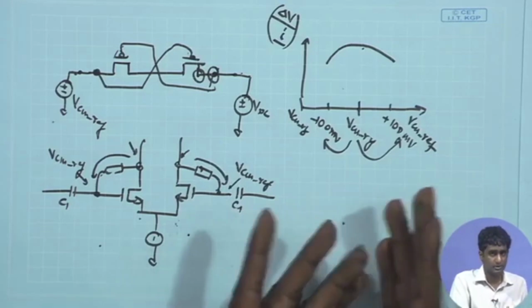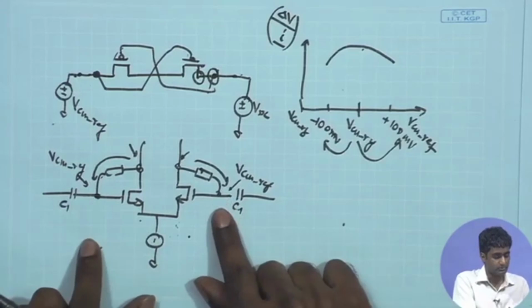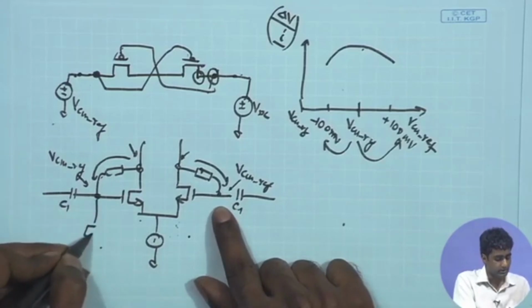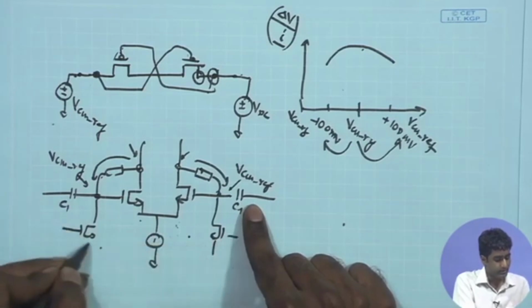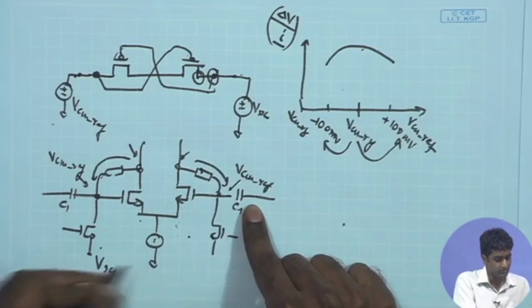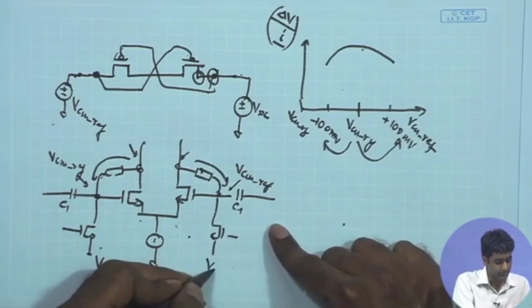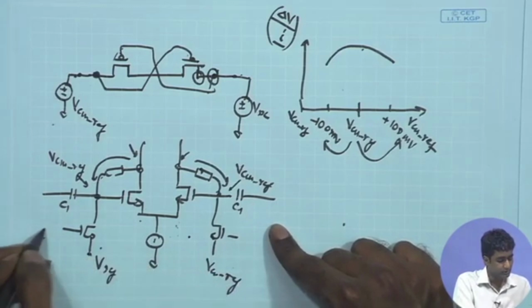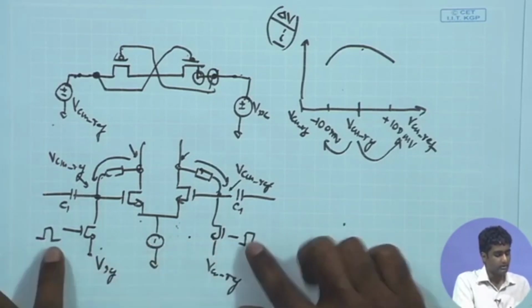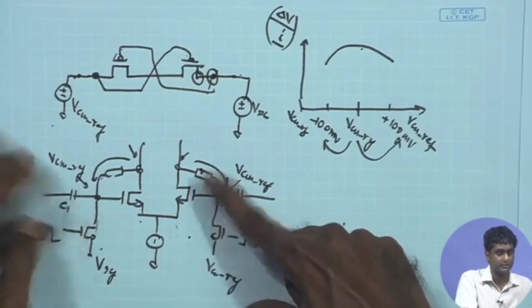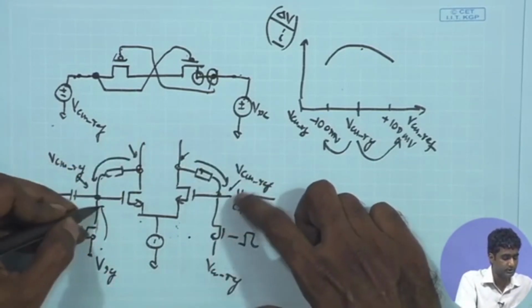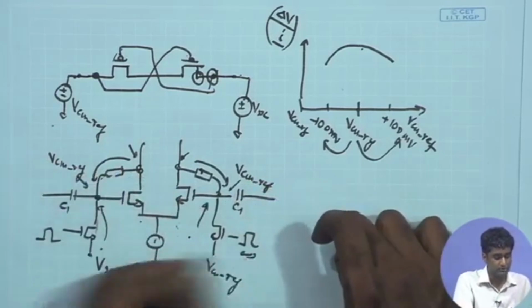So, the other option, if you want to use a DC source, is to connect some switches over here, and at t equal to 0, you provide a DC potential over here, which is equal to the VCM ref as you suggested, VCM ref, and here also VCM ref. You can put this on for a very short time, and since the transistor resistance is anyway very small compared to the others, this will ensure that it gets charged quickly, and this duration is very small.